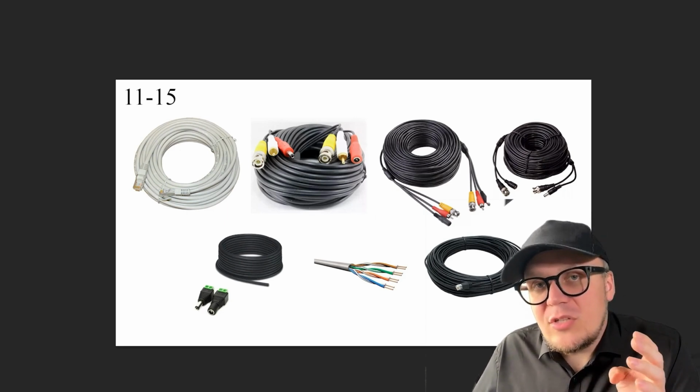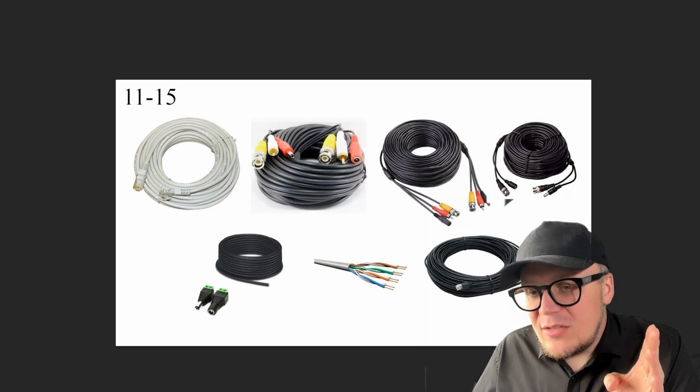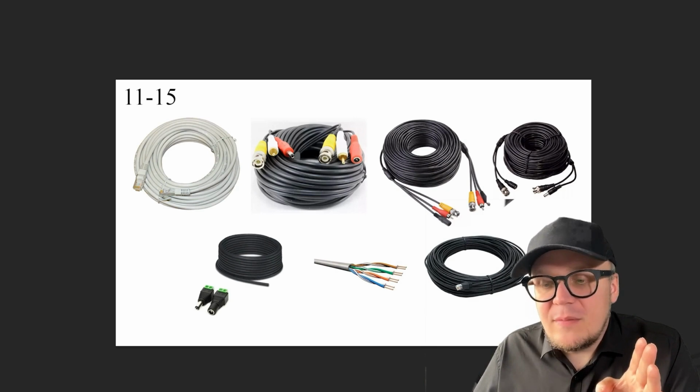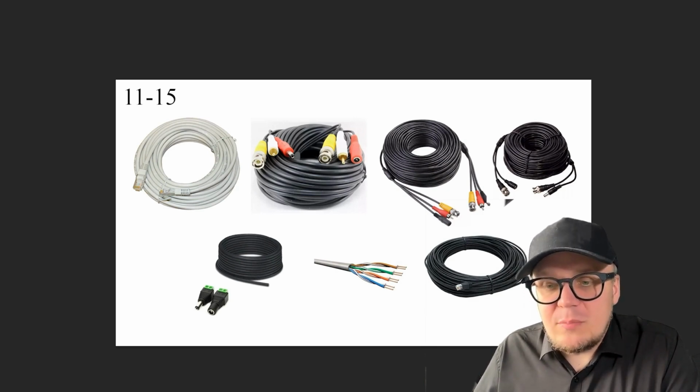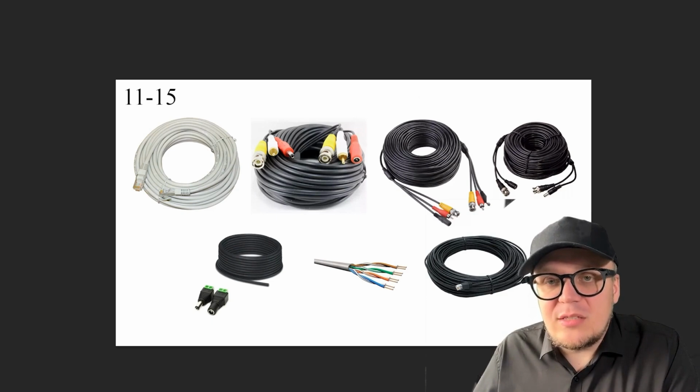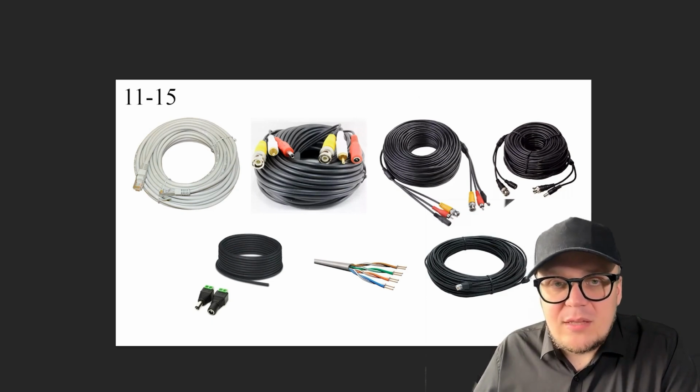Also, a typical situation requires providing UV protection. As for the cable related to AIS equipment, all of it, whether included in kits or purchased separately, already has this protection. If you purchase from another store, be sure to check if the cable you are buying has UV protection. Otherwise, the cable will crack. And then problems with the night lighting will start first, and then the camera will simply stop turning on.